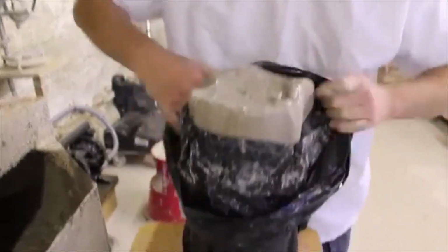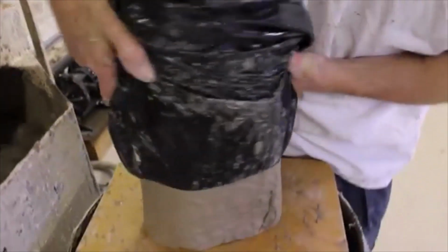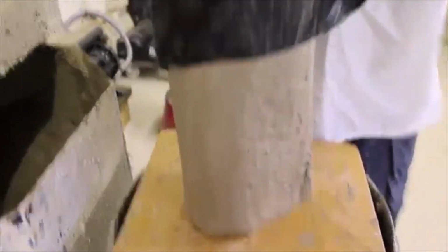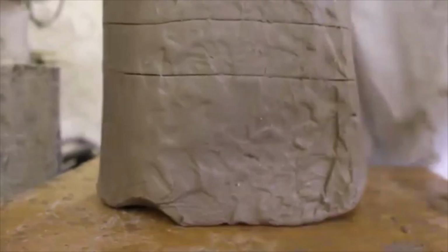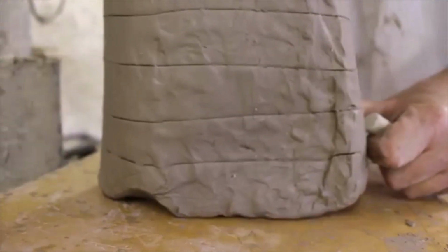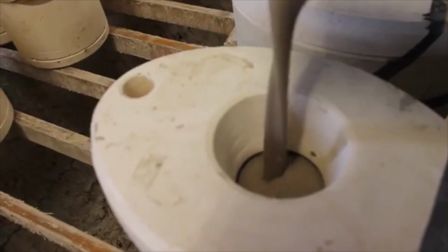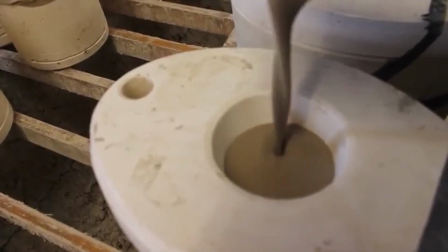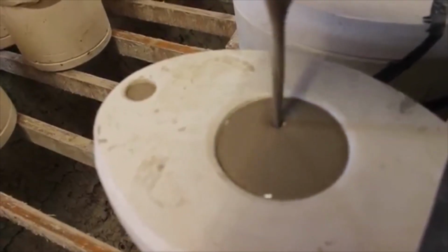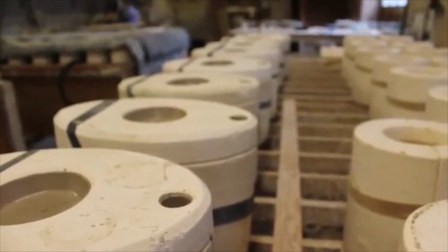The journey of a teapot starts here at the plunger, where a mixture of fresh and recycled clay is mixed with water and strong alkalis to create a liquid called slip. The slip can then be poured into mould designed specially here at the pottery, and then are left for 45 minutes before they can be tipped.